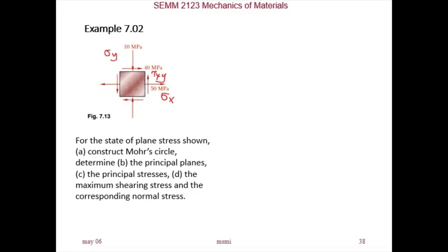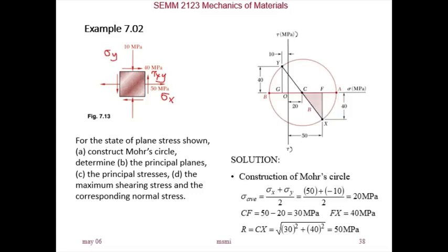So this is the same example as before. So you draw the Mohr circle. What you then draw is, first you plot point x. Point x is 50 and 40. So point x is 50, 40. It's shown here. That is sigma x. That is tau xy. Sorry, it's counterclockwise. So it's positive downwards or counterclockwise. See the arrow here? The arrow shows direction is counterclockwise. Right? So that gives you point x.